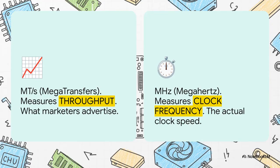So to get to the bottom of this, we need to understand the difference between two key terms. On one hand, you have megatransfers per second, or MT/s. This is what marketers love to advertise because it's the bigger number, and it measures total throughput. But on the other hand, you have megahertz, or MHz, which is the actual speed of the clock. They're measuring two very different things.